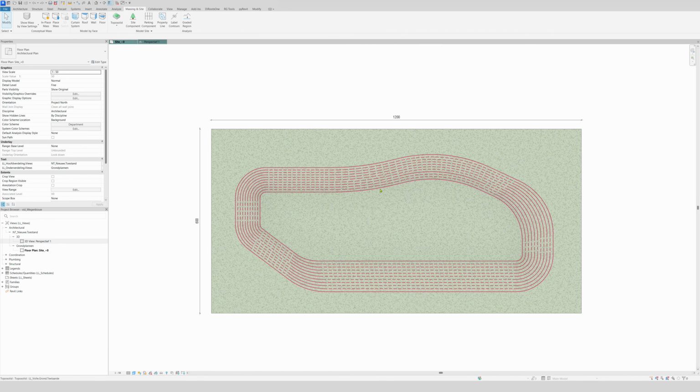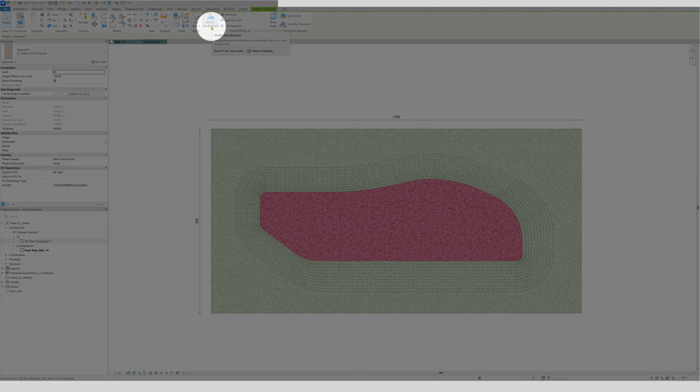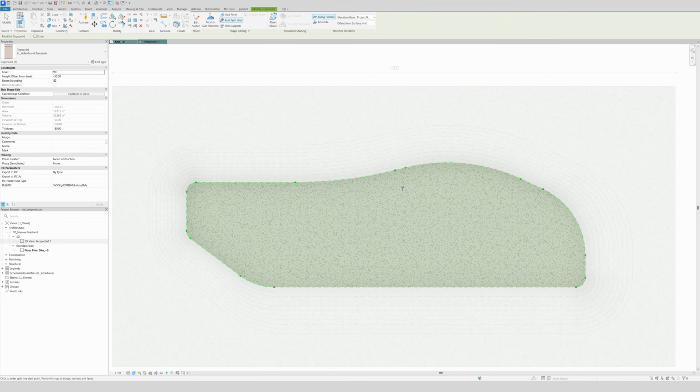Very simple. So we're going to select our base, and then we're going to Modify Sub Elements right here, and now we're going to split a line. For example, I will use, maybe we can split it from here to here, and from the middle to here to here.